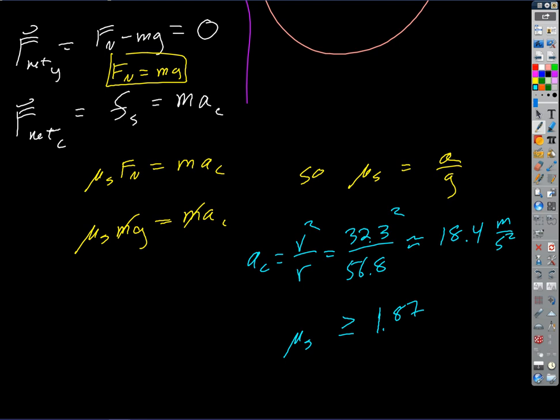So if we plug into this equation, mu sub s equals centripetal acceleration divided by g, what do we get? 3.20 divided by 9.8. Not enough, is it? That's going to be around 0.3-ish. We only get 0.12 for our assumed inclement weather static coefficient. So it's not enough. We have to bank this road a little bit, don't we? So how could we look at that?